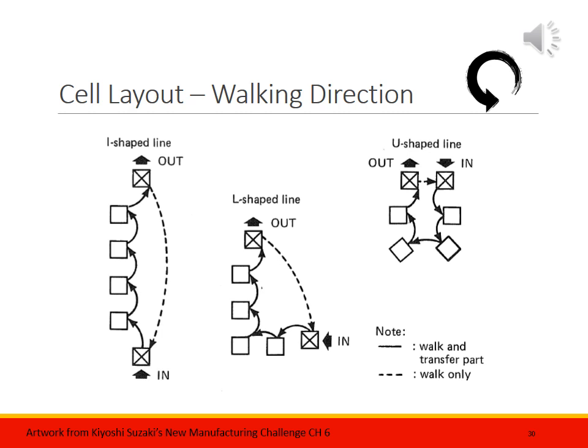Well, first and foremost, you don't automate everything. You have a lot of manual operations and quick, fast hit manual operations. And number two, you can flex the manpower. You can have a cell that runs with one person. You can use that person someplace else in the facility where the demand is higher, because hopefully your manufacturing plant isn't just a snow shovel plant, right? So when you can flex your manpower, and that's why you cross-train, so that you can expand your muscles when you need to in a cell by putting 2 or 3 people in there to really make that thing run to meet demand.